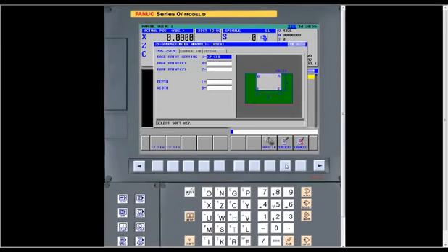You select that, and again, it's just fill in the blanks. What's good about it is, like here, it's asking where you're defining the geometry of your groove, either Z minus or Z plus. So it just depends on how your print is toleranced, whether it's giving a dimension to the front of it. So it makes it very powerful. A lot of them always go to the back of the groove. With this, you can go either way.